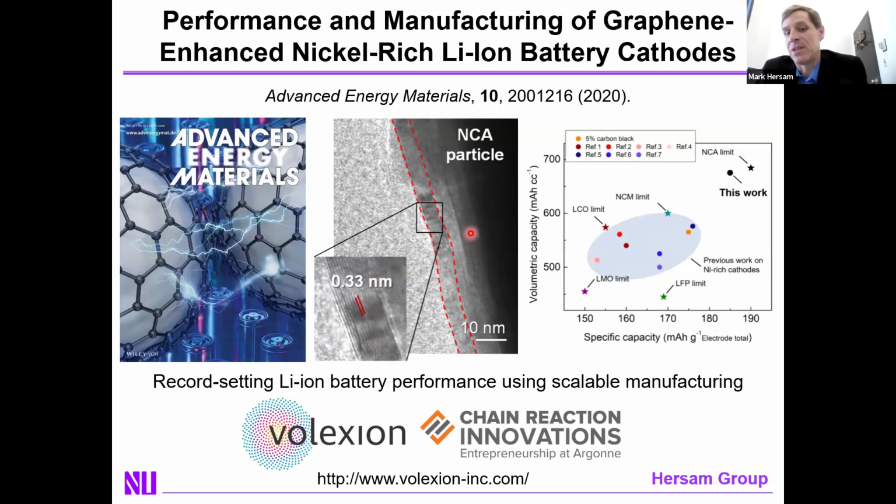And when you get now down to the 0.5 weight % limit for the carbon in your electrode, this becomes cost competitive. It also implies that you can minimize, if not eliminate, the typical conductive additive in a battery, namely carbon black. This instead is a conformal conductive additive, which takes up essentially no space. And as a result, not only do you get a gain in the gravimetric capacity, but also the volumetric capacity approaching theoretical limits at the electrode scale.